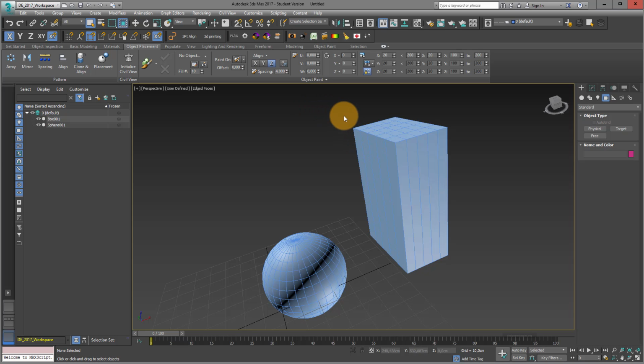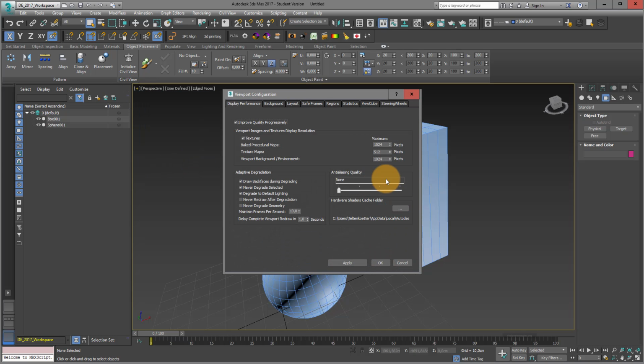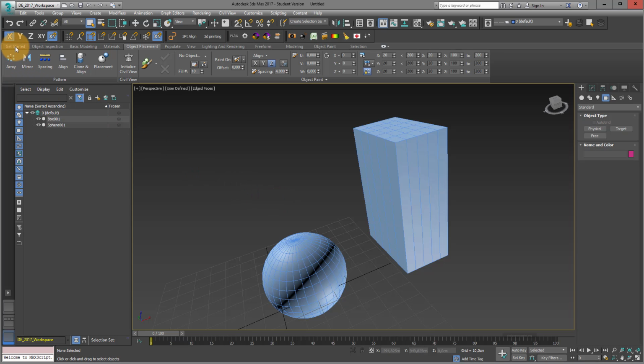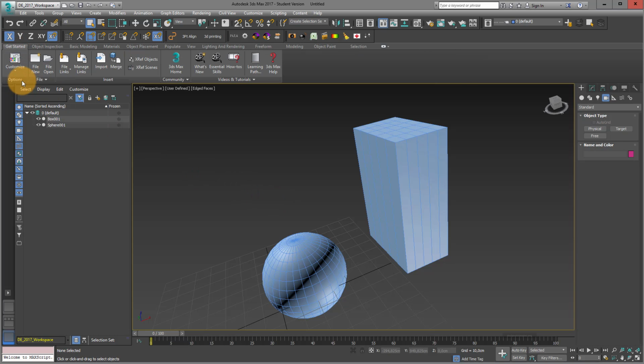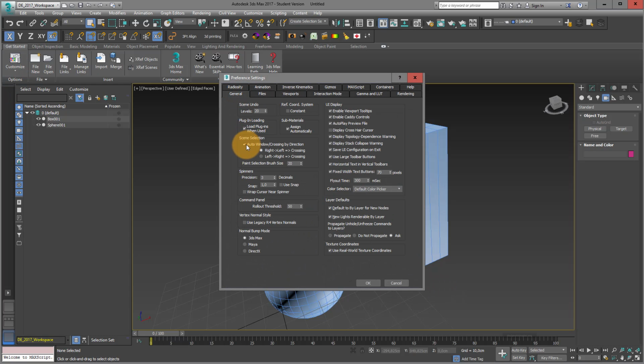So normally it's like this. If you go there and you have the full window, then you have it selected. If you go to this setting and only select the corner of a small object, then also the object is selected. But what I have set up in my customize preferences, I went to auto window crossing by direction, which I think is much better.